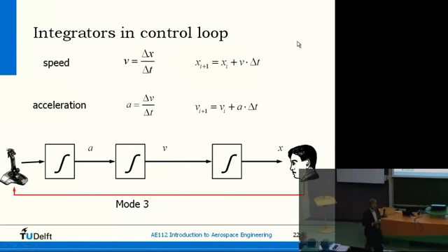The chain, how do they do this? Well, that's a bit complex to tell. It has to do with aerodynamics. At some point, you automatically get the extra integrator due to the aerodynamic properties of the airplane. So this is what you normally get with a stable aircraft. You control the acceleration. You induce a force, basically, or a moment. But sometimes you get an extra integrator, especially at low speeds. In fact, there is a famous example of the...